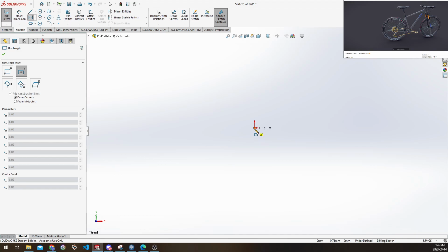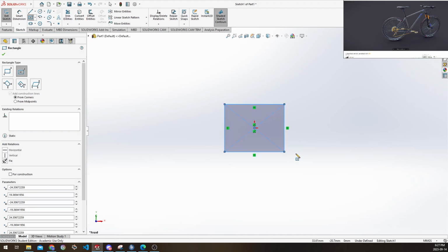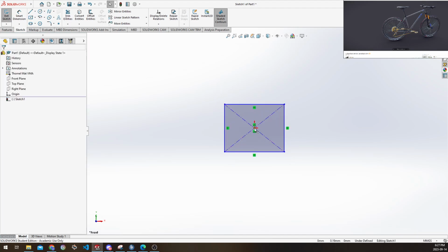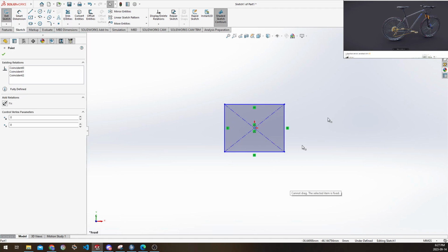You can see that at the bottom right corner of my mouse, there's a little intersection constraint that pops up. Somebody mentioned that in the classroom yesterday or last week. That basically means that the point I'm clicking is going to be on a line, in this case our origin. So once I click off and make this, I won't be able to move the square anymore.